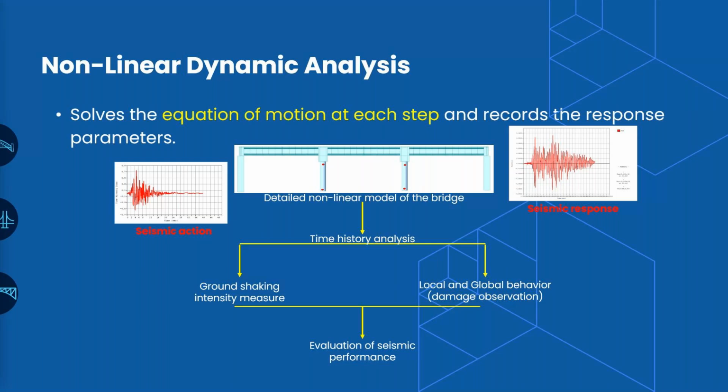Also, the pushover analysis is basically a single mode analysis, we could say. We saw that the loading pattern that we have in the case of a pushover analysis is basically with respect to uniform acceleration, or it is based on the first mode or the fundamental mode of the structure. And hence, it is only considering a single mode as a representation of the structural system. However, we know that the whole structure is multimodal in nature, so it is required to consider all the relevant modes of the structure in the analysis, which the pushover analysis could not consider.